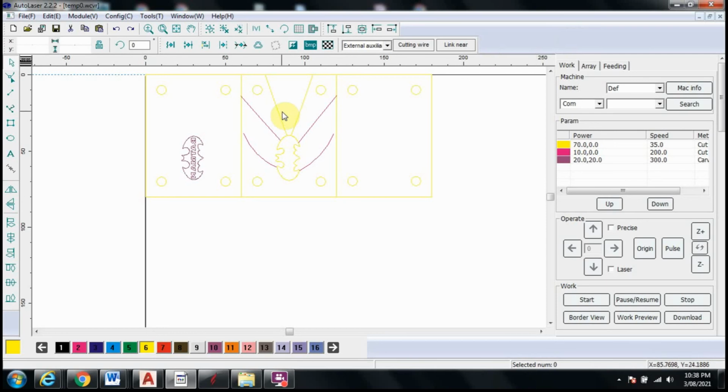The other thing you can do here is to use your selection tool, select all of your pieces on the screen, and then define the size of material that you're going to need at a minimum for cutting this out. You can use this here and add about 10 millimeters to each side. So I'd be looking for a piece of MDF that's at least 190 wide by 90 millimeters tall, and once I've found that, I've then got that to go into the machine. So at this stage, you know what size material you need, you know how long it's going to take, you've got all of your cut settings properly organized and set up, and you've got this in the right spot.